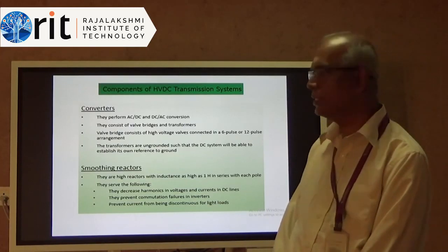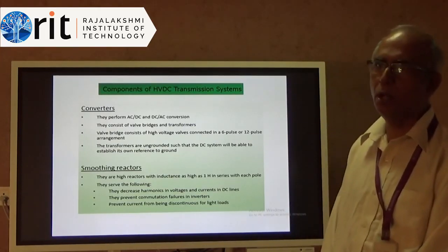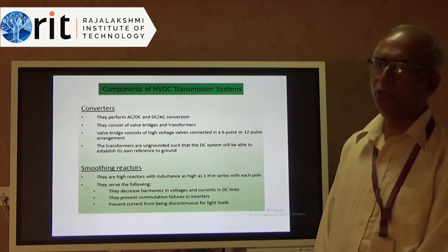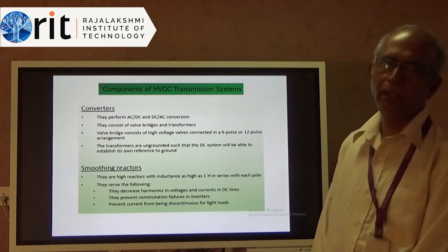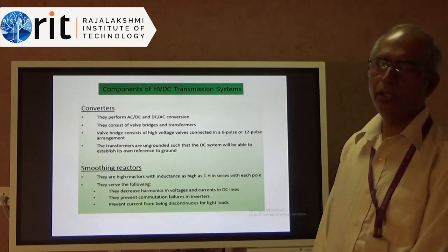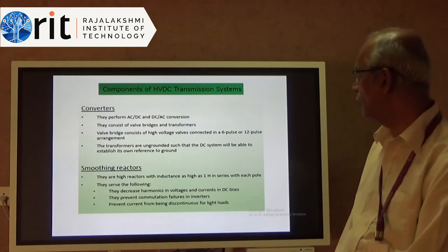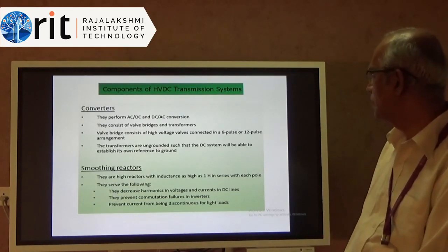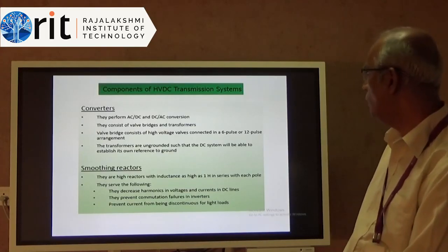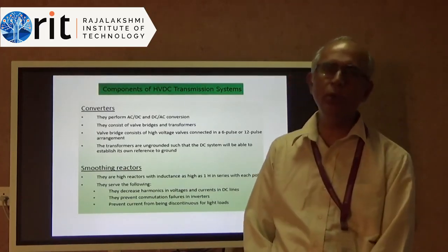You have valves, right? The term which is used is known as valves from earlier times. After valves we had thyristors and so on. IGBTs are there, but still the old terminology is still there, so people continue to use this term valves. So transformers of course will be there. So valve bridge consists of high voltage valves in two configurations, 6 pulse and 12 pulse arrangement, right?